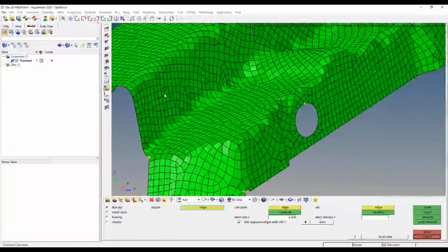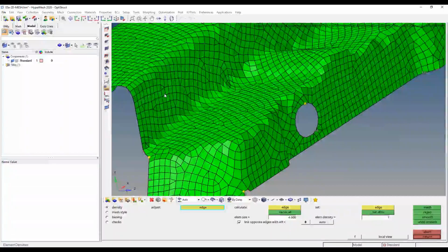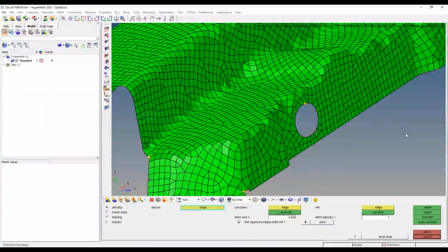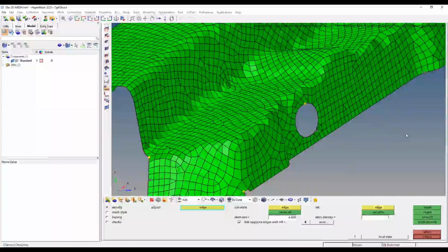So definitely there's benefits to having them. We want to try to find that sweet spot of what are unnecessary feature lines or surfaces that I don't need to ensure I have elements or nodes at. Because the biggest thing to remember is that those surface lines are giving a kind of guide or a skeleton for the mesh to ensure that it's always going to have nodes at those edges. So you don't want to just turn off every edge.